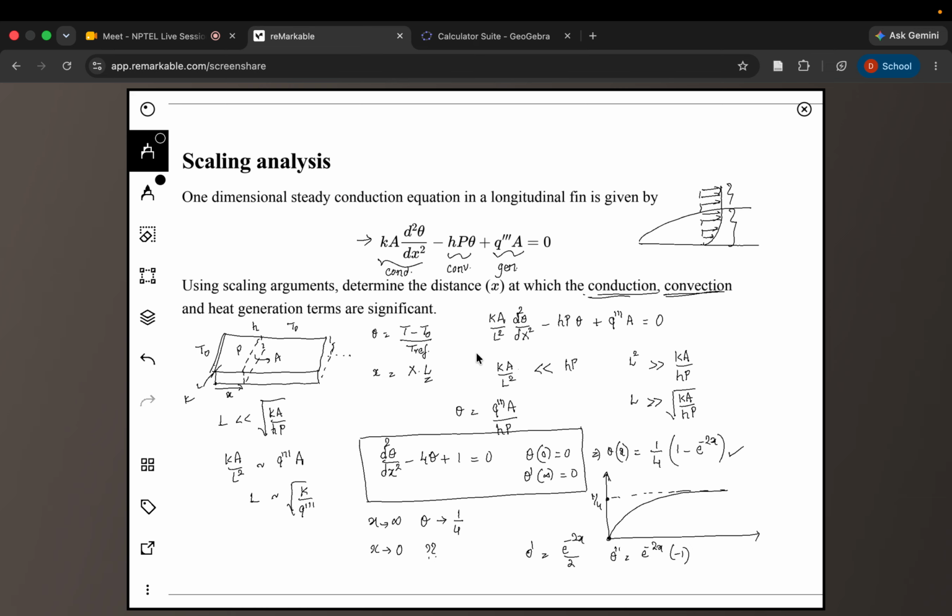And then as we go far away from it, this is where your Reynolds number, that is inertia versus your viscous effect, comes in. If you write the boundary layer equation, you'll have u times del u del x plus v times del u del y, minus dp dx times 1 by rho, plus nu times del square u del y square.